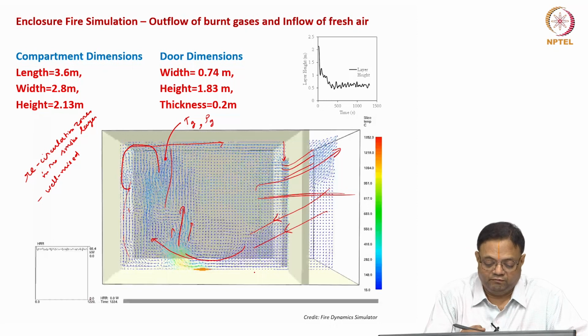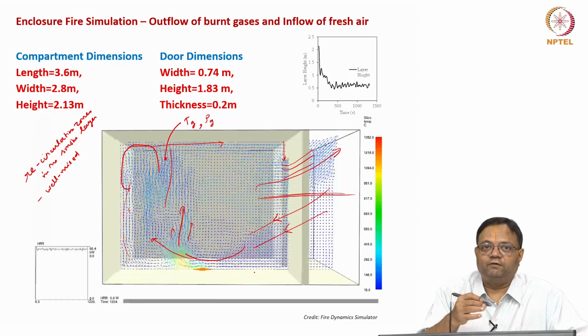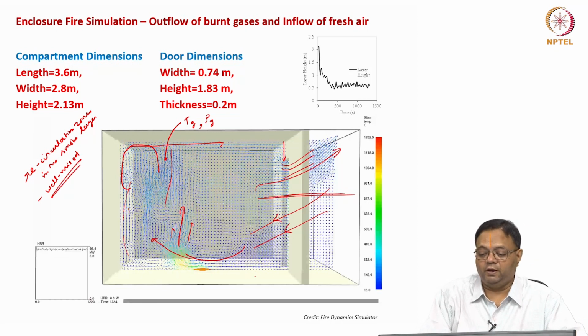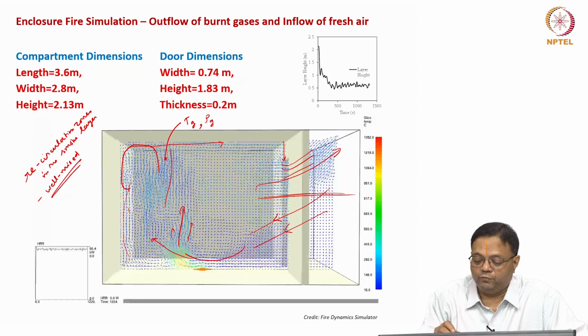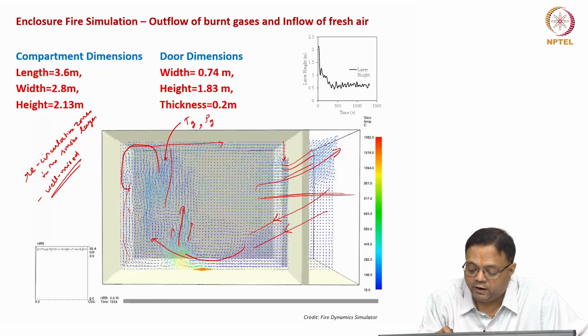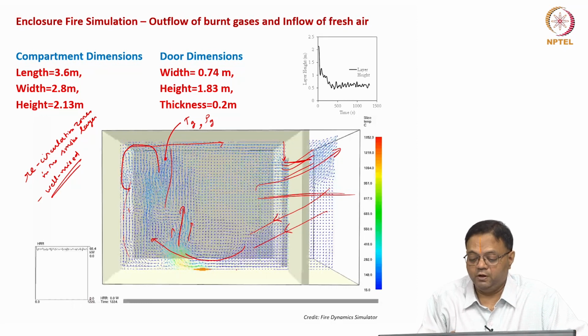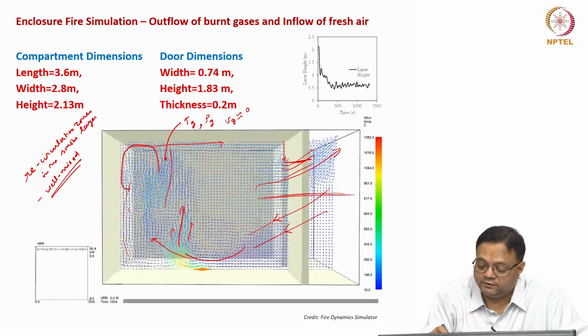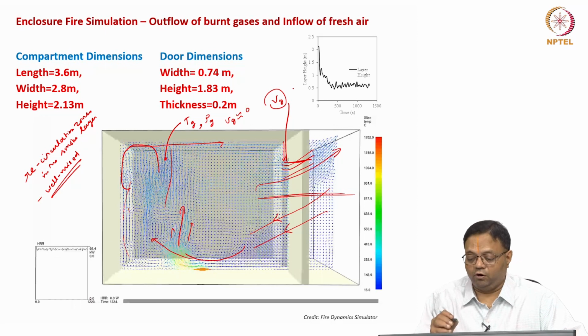That is fine, which is actually shown here because of the convection. The well mixed condition is reached, so that assumption can be valid. Now you can see that the velocity values are very low here, and suddenly in this exit opening the velocity is high. At the far field, recirculation zones are there, the velocity value will be tending to 0, but at the exit plane the velocity value will be finite.